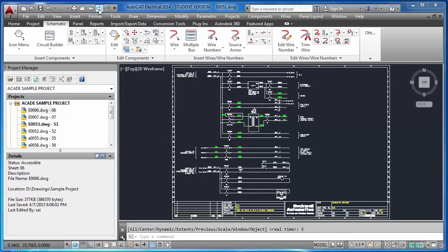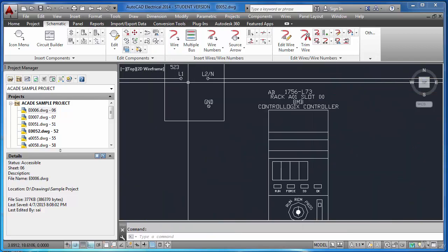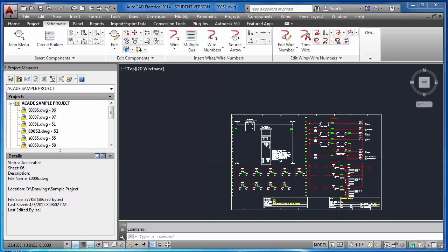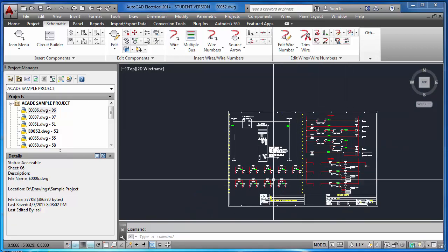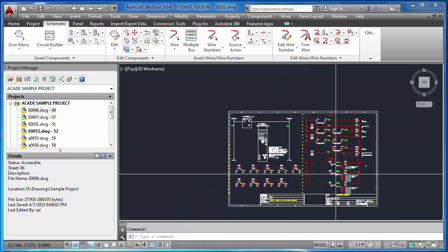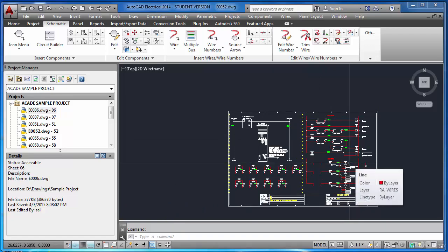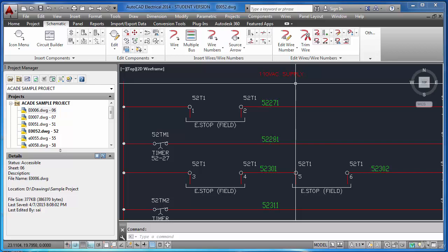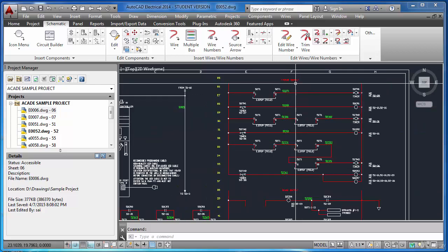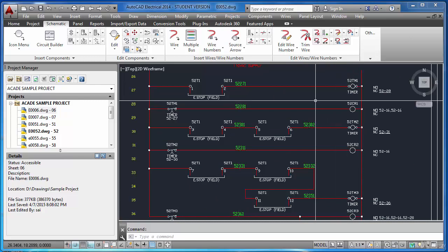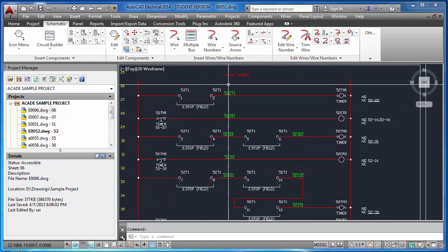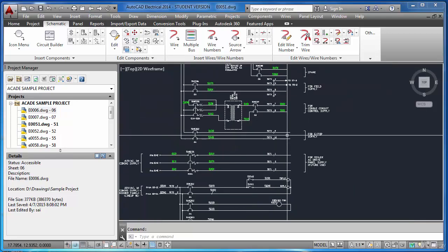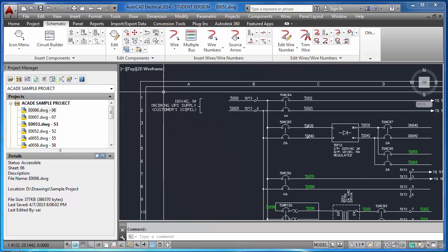And next sheet, this is again the power supply of the control logics, and here you can see these red lines, these red wires. This is basically the control circuit. This first one, 110 volt AC supply, this is basically an emergency circuit. So 110 volt AC we have to feed here from the previous sheet. If you see here, this is basically 110 volt AC supply.